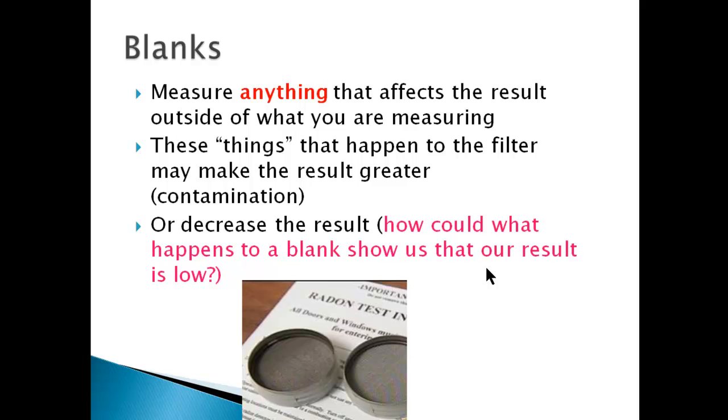That's one thing. One thing that is really obvious in radon testing, and I'm really familiar with charcoal canisters. These are charcoal canisters that you just open up in an environment. The radon in the air gets adsorbed onto the activated carbon in here. So it's important when you're making measurements with charcoal canisters to use a blank because of the moisture in the air.